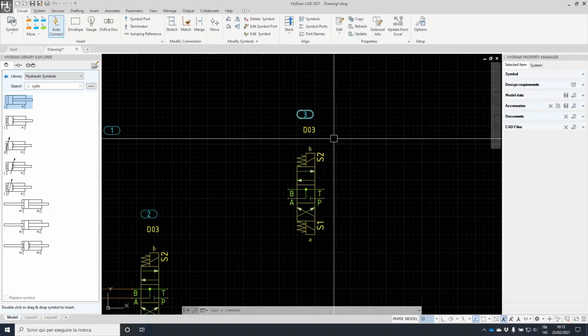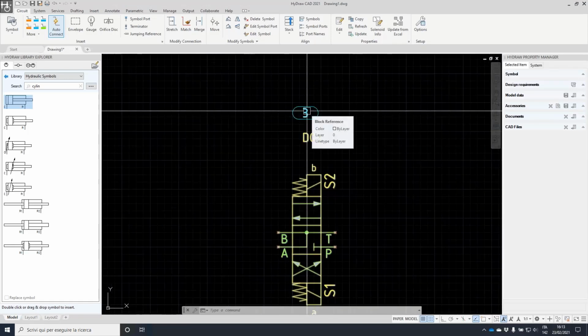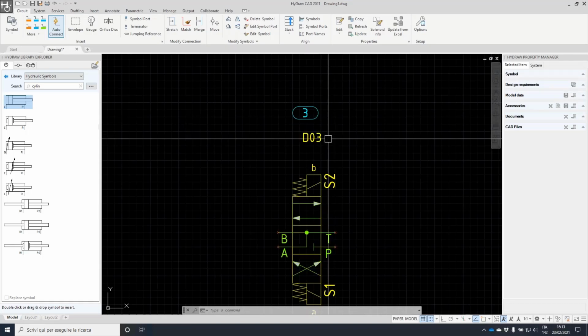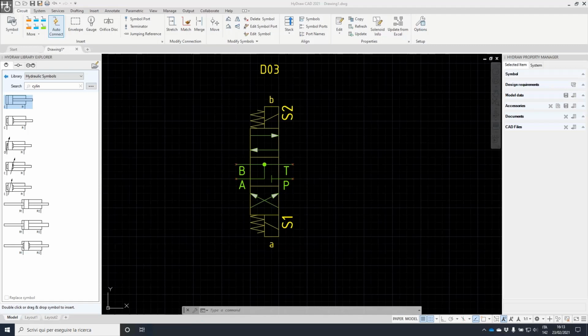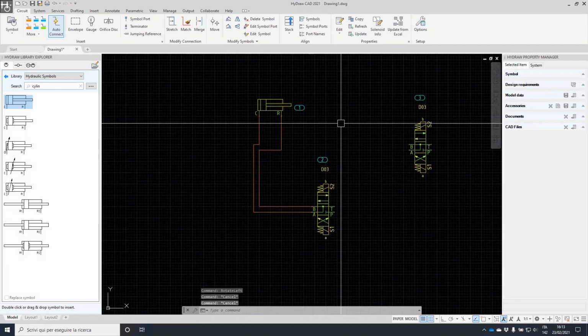We apply a rotation also on the position for item ID and the display formats. And if you notice, the text now has rotated vertically. So basically, if you have defined the display format for a symbol inside the boundary of the symbol itself, then the display formats will rotate together with the symbol in order to keep the same standard geometry that you expect for that particular symbol. So we hope that this will help and save time when doing editing or modification on a symbol.